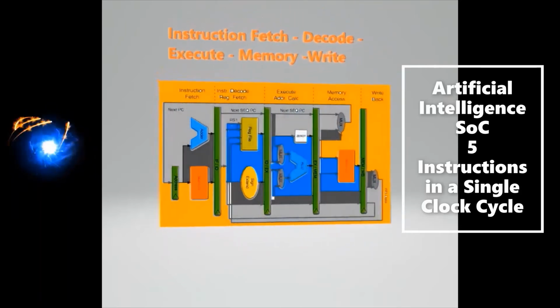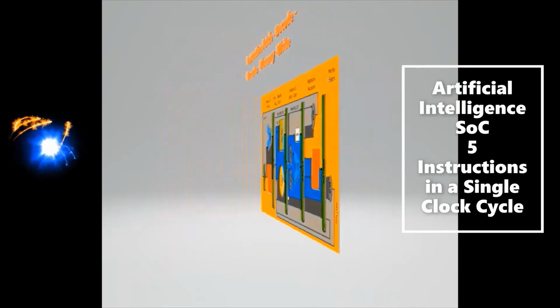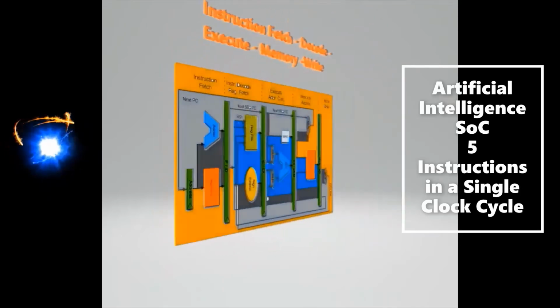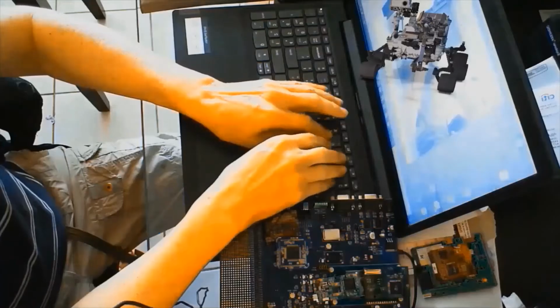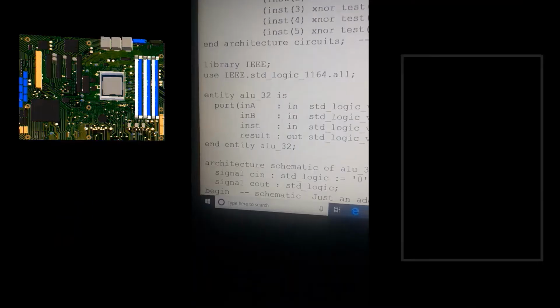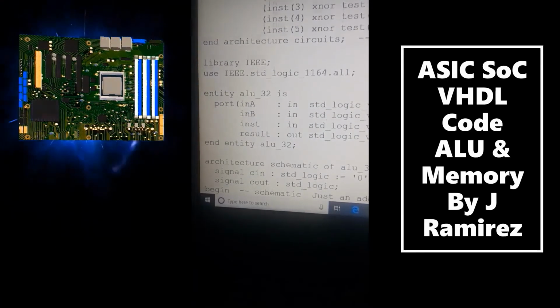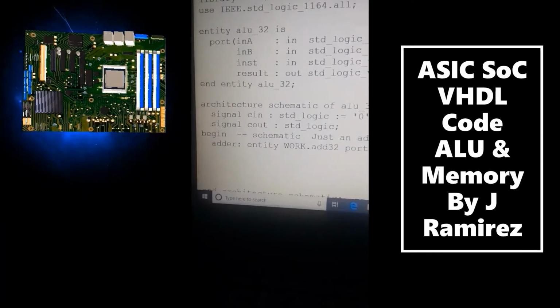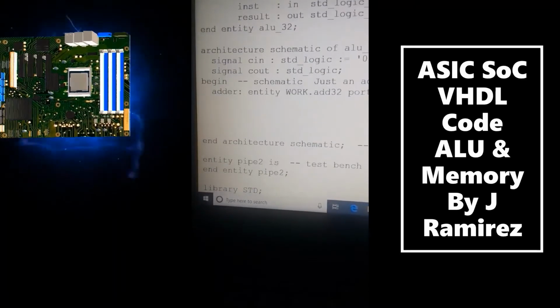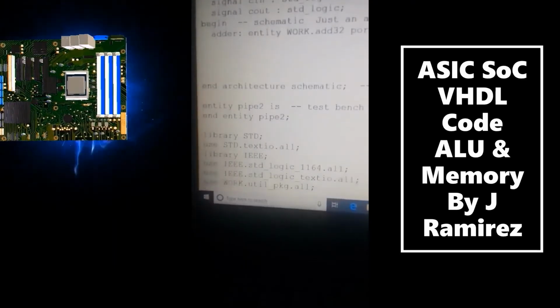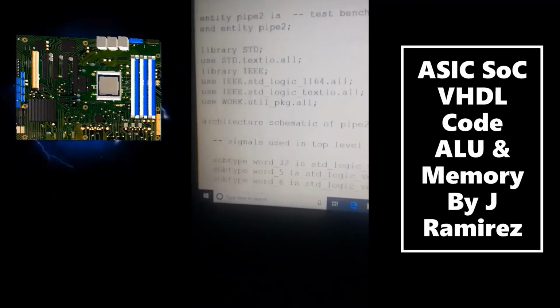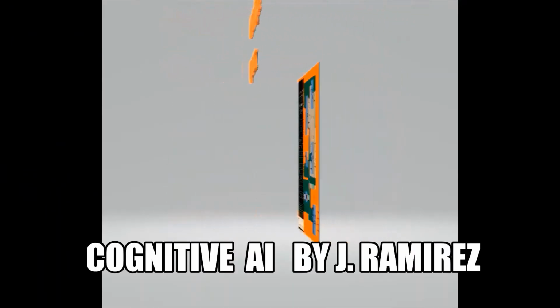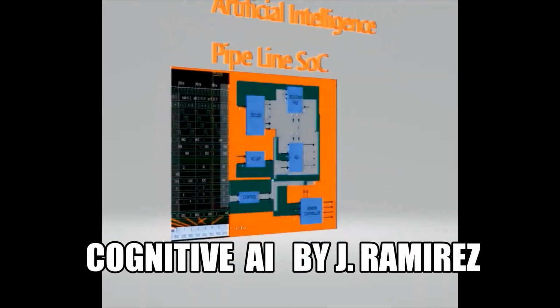The system on chip SoC VHDL file defines a package declaration and body that defines the functions of the 32-bit and 5-bit register entity with clock and clear inputs, an instruction memory entity, and behavioral architecture.